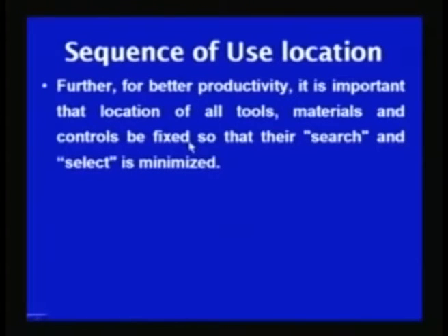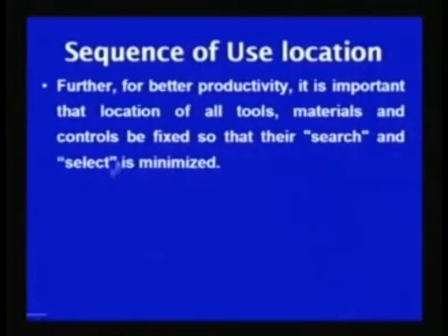It is not necessary that the control devices should be located only in light of the principles of motion economy. It should also be seen that the control devices, tools and materials are located in such a way that the search and select related activities can be minimized, so that the time required for carrying out the job can be reduced and the operator efforts also can be reduced.